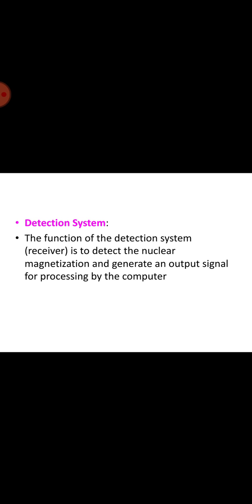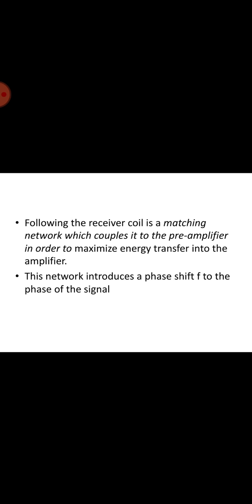The RF signal constitutes the variable measured in magnetic resonance tomography. These are extremely weak signals having an amplitude in the nanovolt range and thus require specially designed RF antennas. The sensitivity of the MR scanners therefore depends on the quality of its RF receiving antenna. For a given sample magnetization, static magnetic field strength and sample volume, the signal to noise ratio of the RF signal at the receiver is given by SNR equal to K into Q by Vc, where K is a numeric constant, Q is the coil quality factor and Vc is the coil volume.